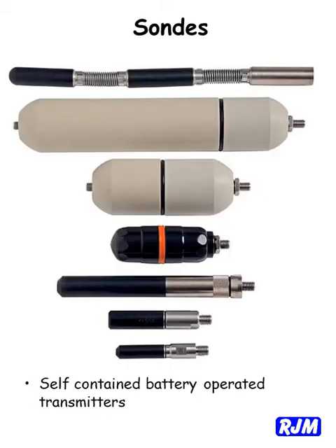Sondes are battery-powered, self-contained transmitters. They can be the most accurate way to locate conduit, storm, and sewer drains. Cast iron blocks most of the signal from sondes. If you're locating cast iron, connect the transmitter to the cast iron or ductile iron pipe.